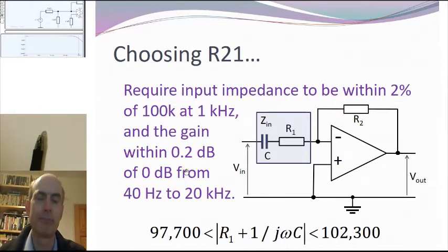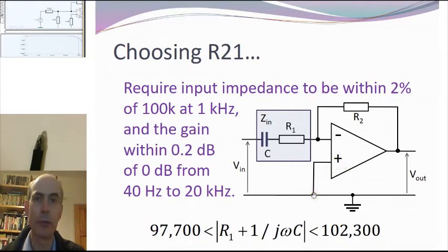specifications achieved? Well, first of all, the input impedance. For a summing amplifier like this, this node is known as a virtual earth point. It's held at ground all the time. It is at 0 volts, but it's not a real ground point because current cannot flow directly from it to ground. We know it's at 0 volts because the op-amp is not saturating, and an op-amp which is not saturating is trying to get its two inputs to be at the same voltage. Its non-inverting input is tied to 0 volts directly, so the op-amp will be trying to keep its inverting input at 0 volts as well.